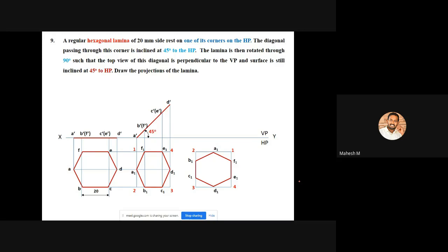Okay. So what's the next procedure? We have to project all the 6 points towards the front view position. So you can create a vertical projection, and also you should create the horizontal projection like this. So each point is having a horizontal line and also a vertical line.